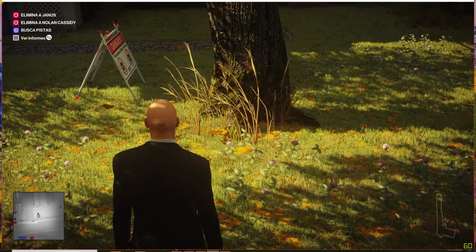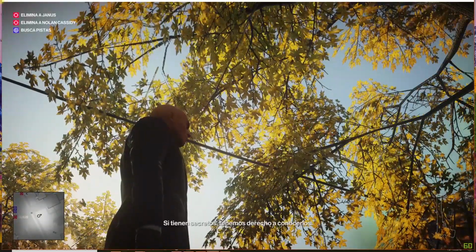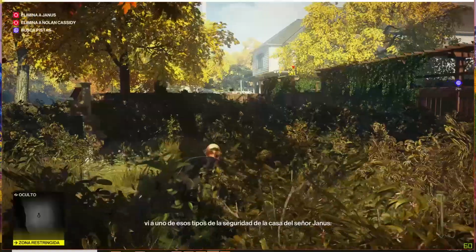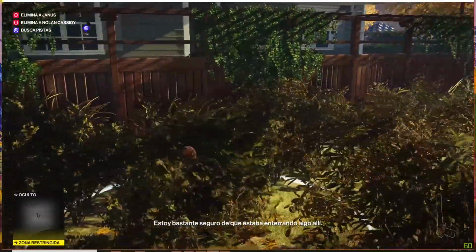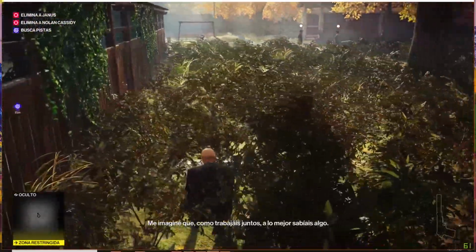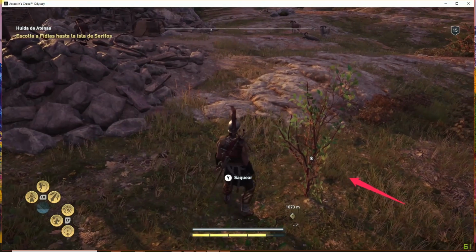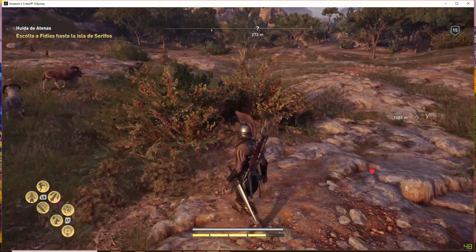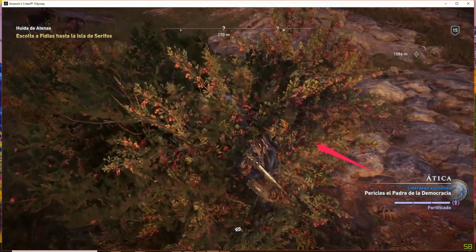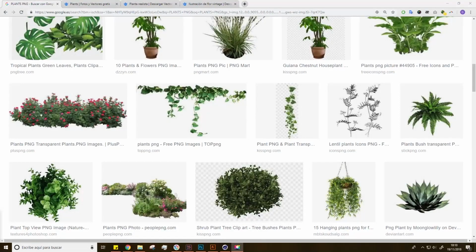We save time processing images. With this method, instead of modeling each plant or vegetation polygon, we generate plants, optimizing the geometry that way. Then we link these plants to textures we have previously created in Photoshop or other more specialized software, like Bitmap 2 Material or Crazy Bump. Thanks to the color, alpha, and normal map textures, we create the perfect balance between the result and the optimization. Okay, that said, let's see how we do it.